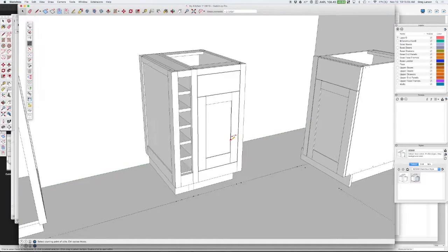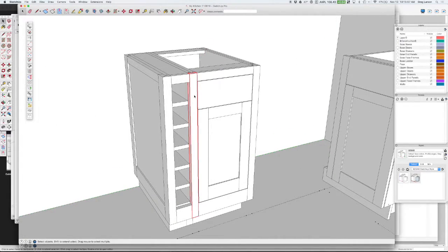The only thing is I've got a little issue going on in here, because remember I've got two styles here, one belonging to this cabinet, one belonging to this cabinet. And I want to make one rail across here. So what I'm going to do is take all three of these and unlock them. So I right click, unlock. I'm going to delete this guy. Notice there's still a style there. It's also locked, so I need to unlock that.